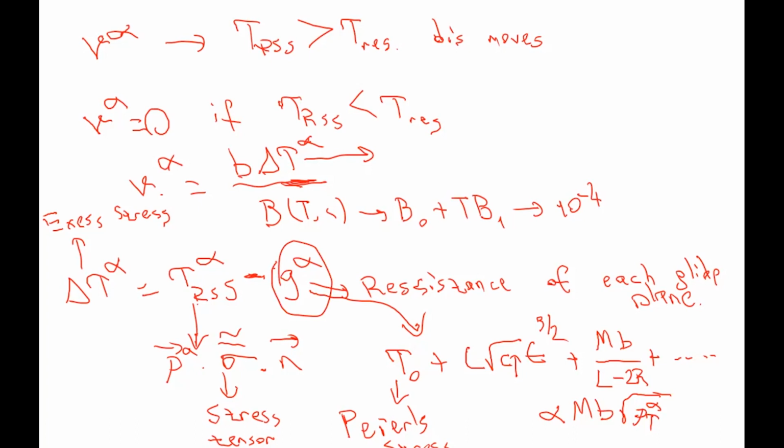In order to overcome this resistance of each plane, we have to increase our resolved shear stress, right? Then we have strengthening. So that is the mechanism.